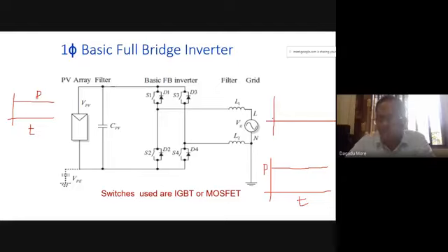But in case of a single phase AC system, assuming the currents are sinusoidal, we have seen that power has two components. One will be DC, plus the other is at two times the frequency. So this will be DC, and then we have seen that the power is fluctuating like this. These are the fluctuations of the power, so this is the AC power, under the assumption that our currents are sinusoidal.